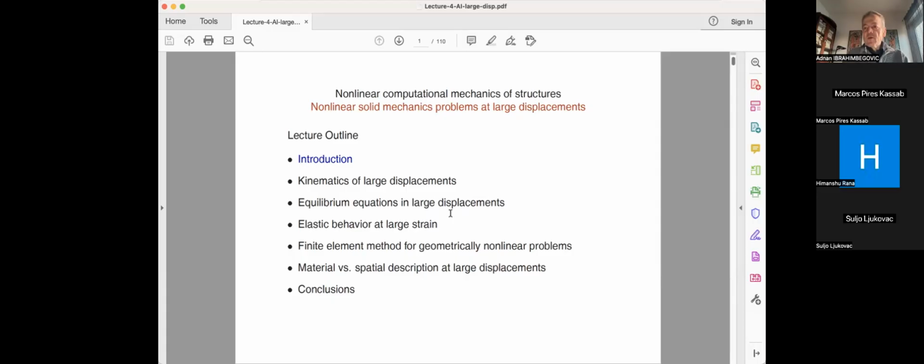Today we'll check a little bit more on that, in particular how to develop this constitutive model for the large deformation setting, and in particular we will need to use these principal stretches. So this reduces the three-dimensional problem to handling principal values, and a big advantage of that is that you separate the geometric nonlinearity from the material nonlinearity. Then you can build your free energy in terms of these principal stretches. It becomes just a scalar potential in terms of scalars, and then you can work it out just like in a simple one-dimensional setting, because you handle one principal stretch at a time.